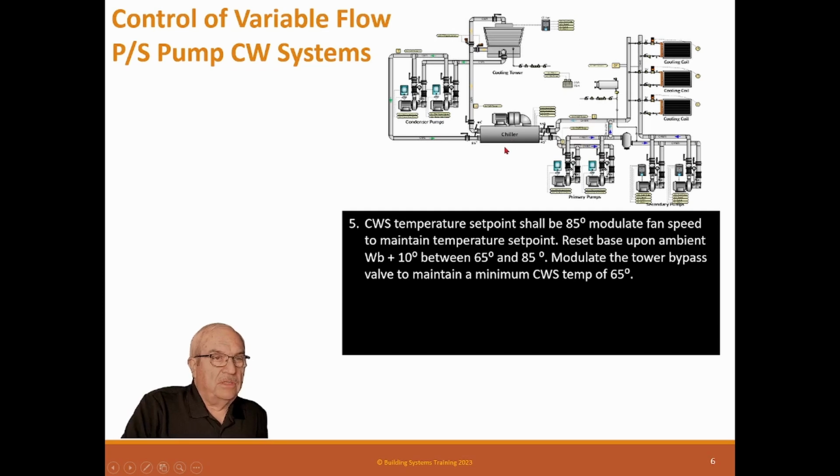Now, we've seen a couple of large studies done on whether that's more efficient than not, because remember, when you lower this temperature of the tower, this fan runs more. But the tower fan, you know, for a 350 ton chiller, it might be a 50 horsepower fan motor. Basically, running this up on the VFD for more time is nothing near what the chiller will save.